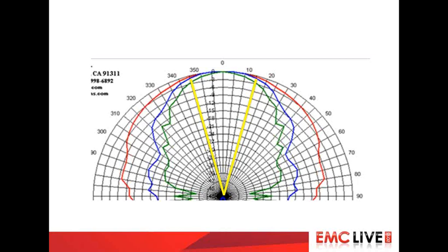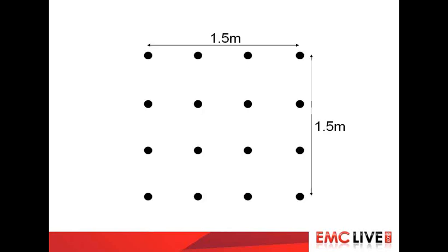We can do likewise with the one at 9 gigahertz. Let's count those off, going clockwise again: 5, 10, 15, 20, 23, 24, let's call it 24. And it's the same on the other side. So at 9 gigahertz, this has a half power point beam width of 48 degrees or thereabouts. And then the final one, for 1 gigahertz, has a very nice beam width of 10, 20, 30, 40, 80 degrees. Why am I saying it's a nice beam width? Well, this system has a job to do. The antenna has to illuminate this calibration plane.